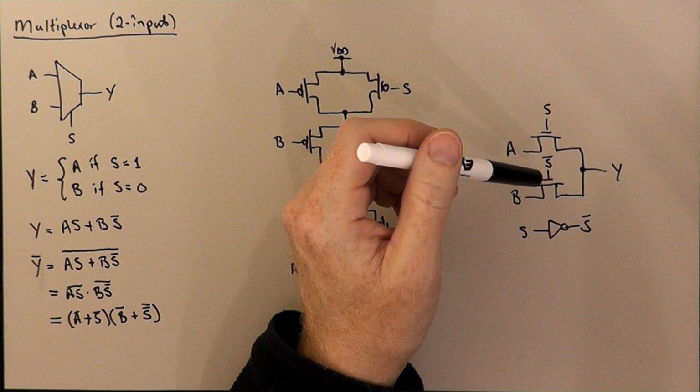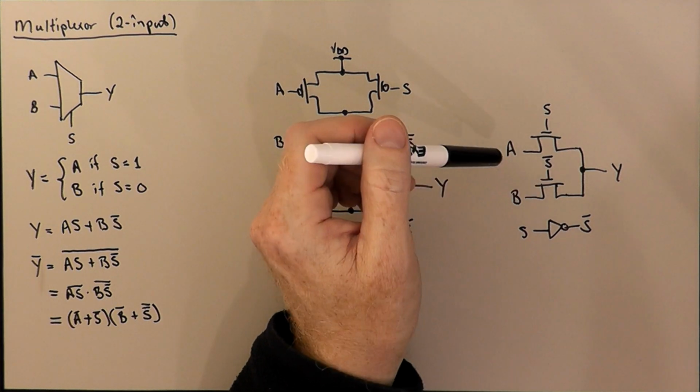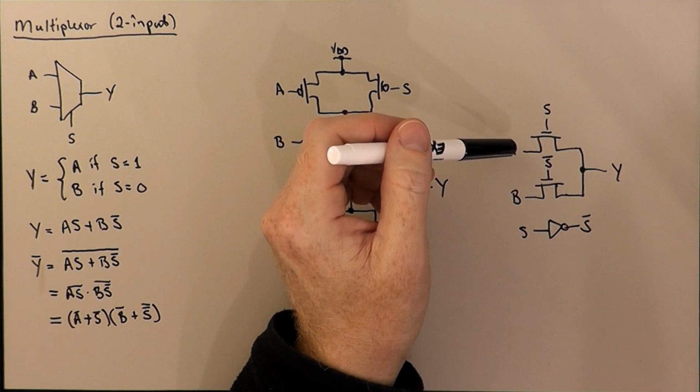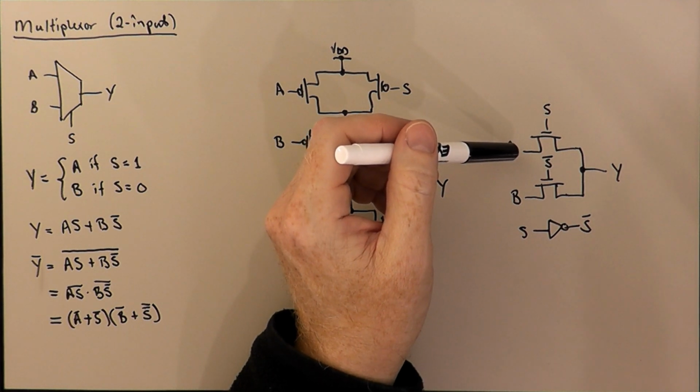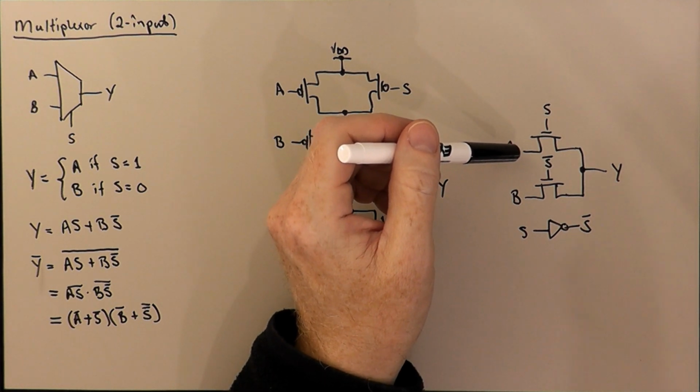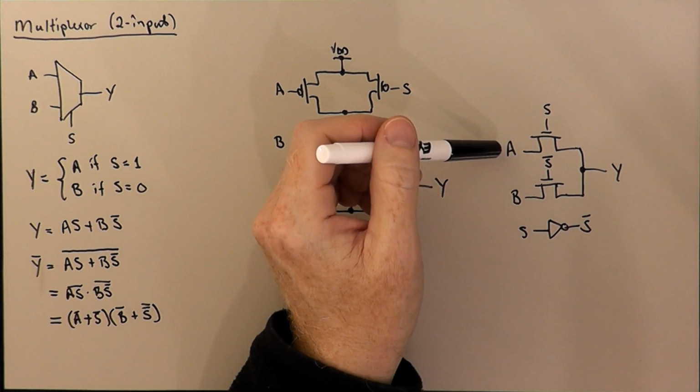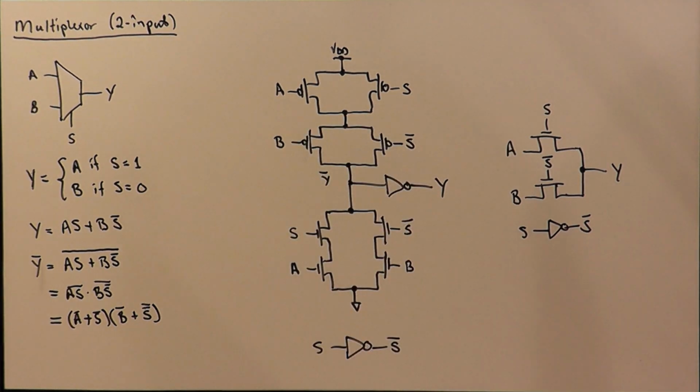The difficulty is going to come in because while NMOS transistors are very good at pulling down, they're not very good at pulling up, which hopefully you figured out in Post-Lab 5, the reason for that. So we would say that the NMOS transistors pass strong zeros but only weak ones.